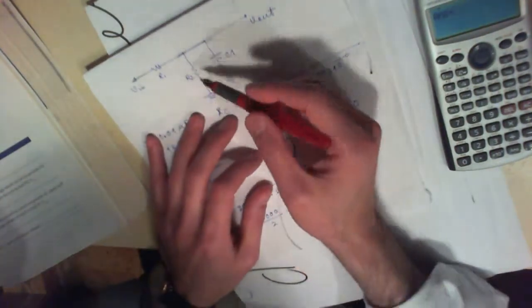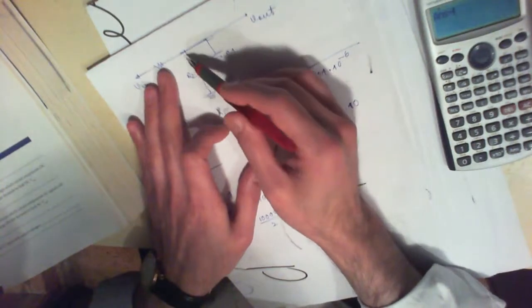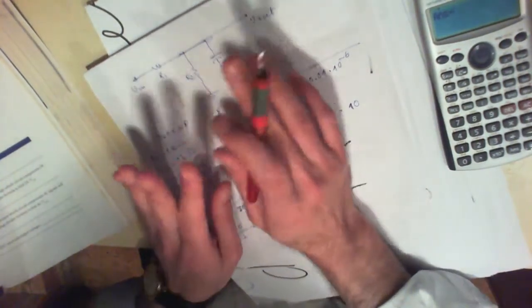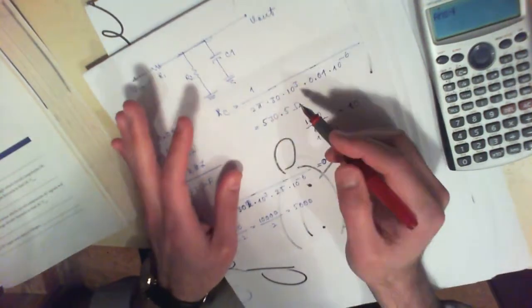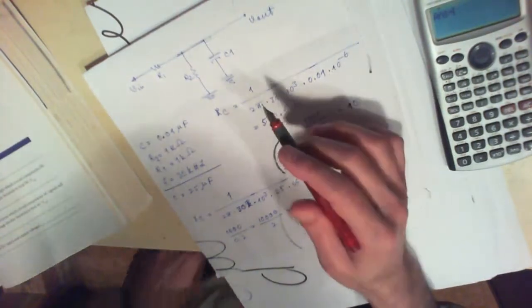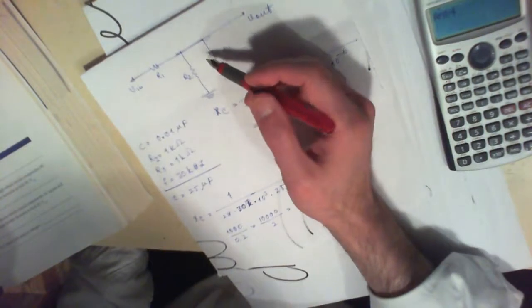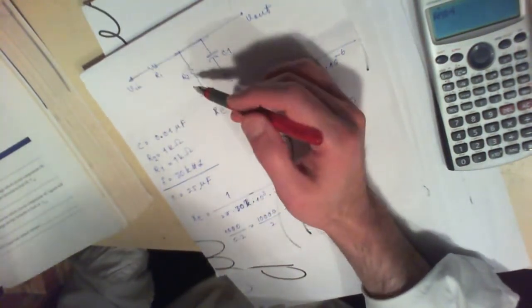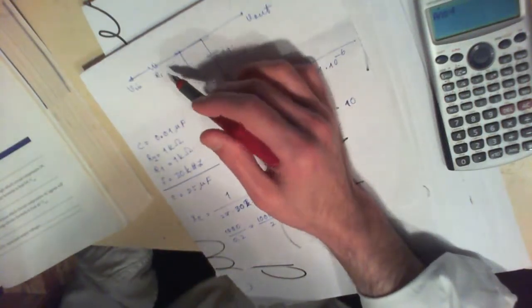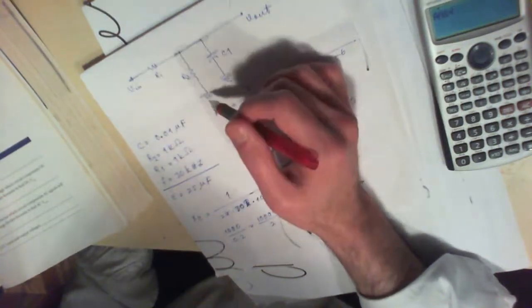You could, for example, increase the value of this resistor so that the ratio is something like 1 to 10, but then that will change other things in your circuit as well. Then that would change the way that the circuit would behave in the case of DC signals coming in.